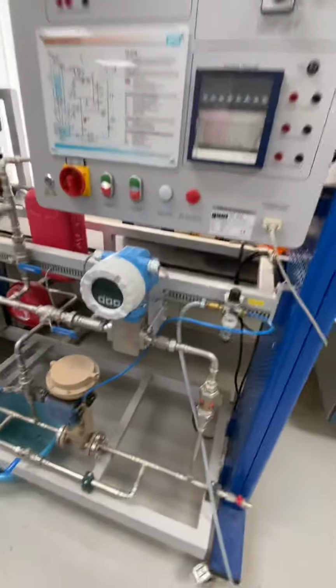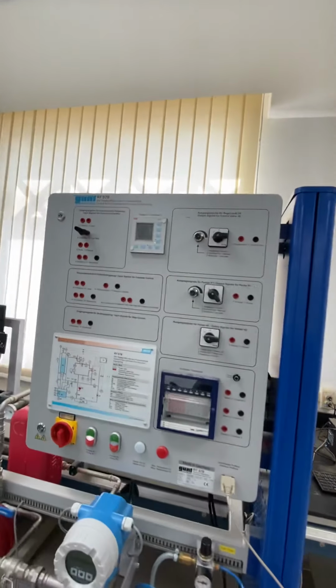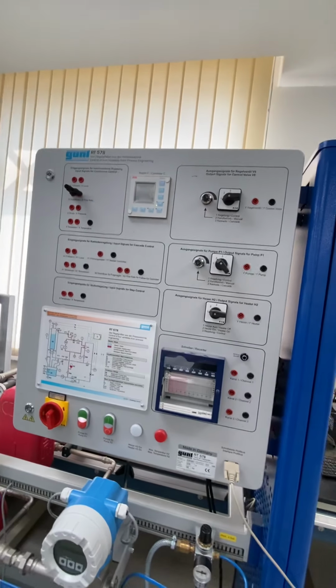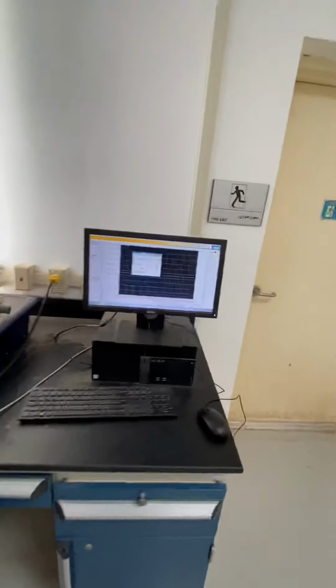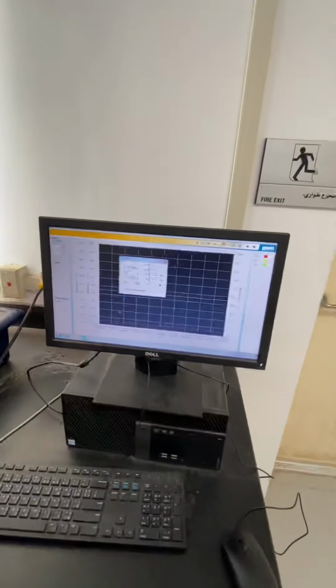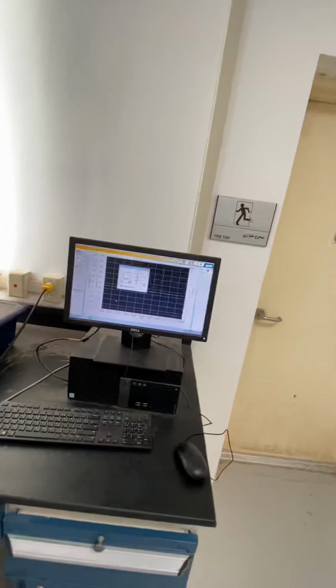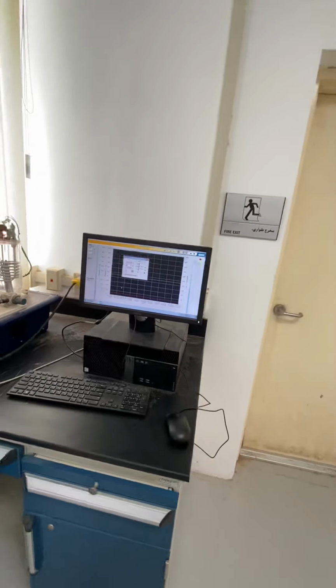There will be zero flow rate, meaning that the process value will decrease. The flow rate will decrease and it will eventually record the zero value. So it means basically that the process value will go below the set point, and since we have a negative error in this situation, the controller output signal will start to increase.